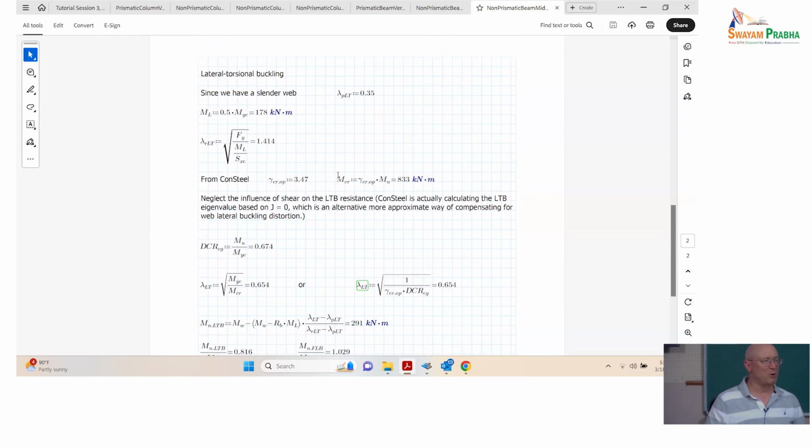And so again, what are we doing? The simplest way to put it here, I want to check the strength of an equivalent prismatic beam that has the same Mu to Mw, if you wish, as this cross section, and has the same gamma critical. And so that prismatic beam is now a surrogate for checking where am I here at this middle cross section. Just did the same thing for the top.